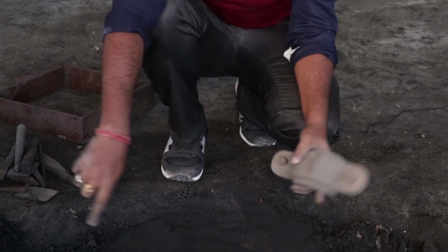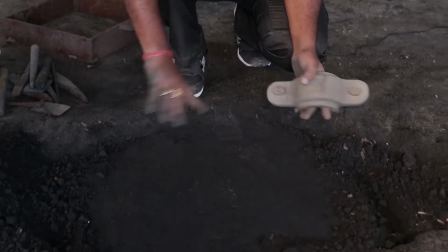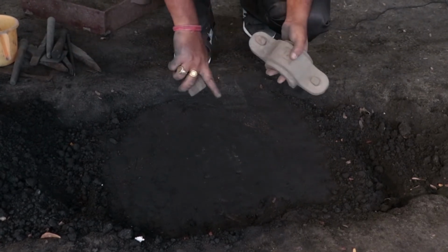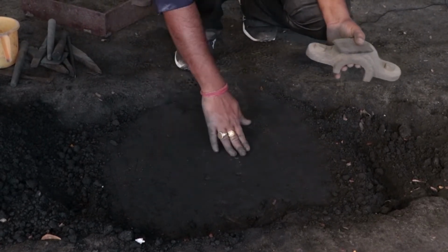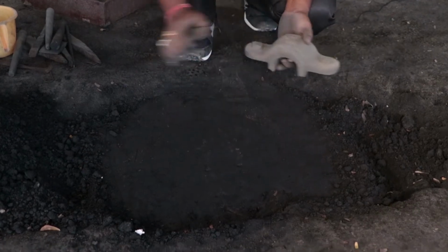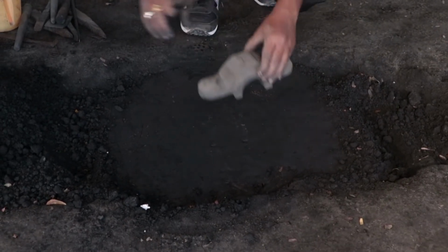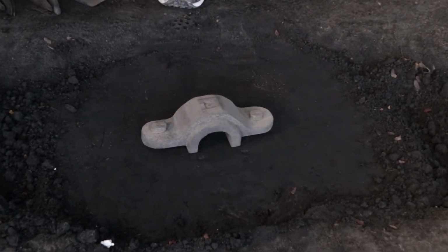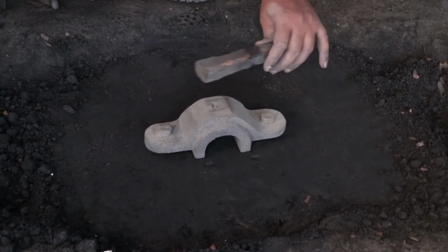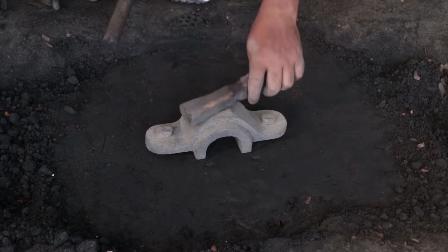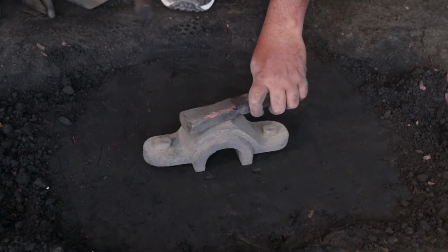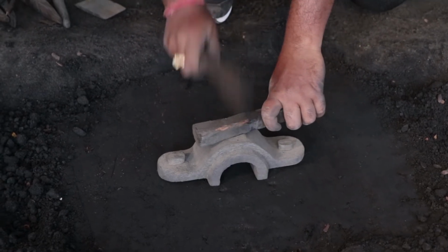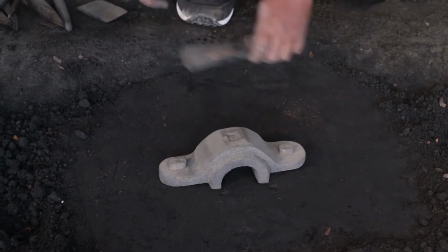First of all, this is the place where we are going to start the job. We need to plane the entire surface and make this totally hard enough. Once this drag is hard, take the pattern and place it over here. Again, with the help of any wood piece and this rammer, we are going to hit it slightly so that it penetrates in the drag.